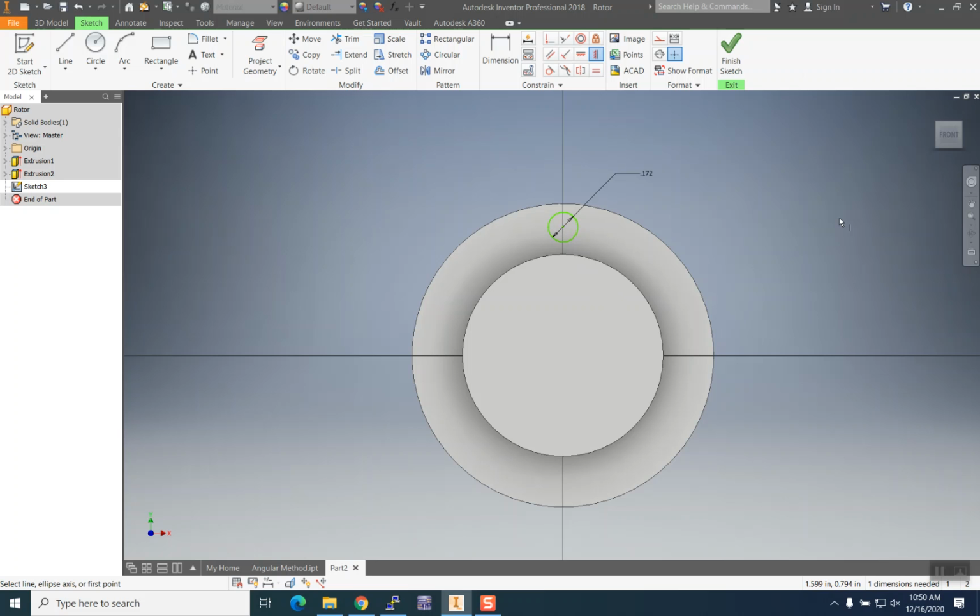Now, again, press F8 to show you your constraints. So I can see my vertical constraint is there. And F9 to hide those. So now if I drag that, I shouldn't be able to drag it anywhere left or right. See, it's stuck to up and down.